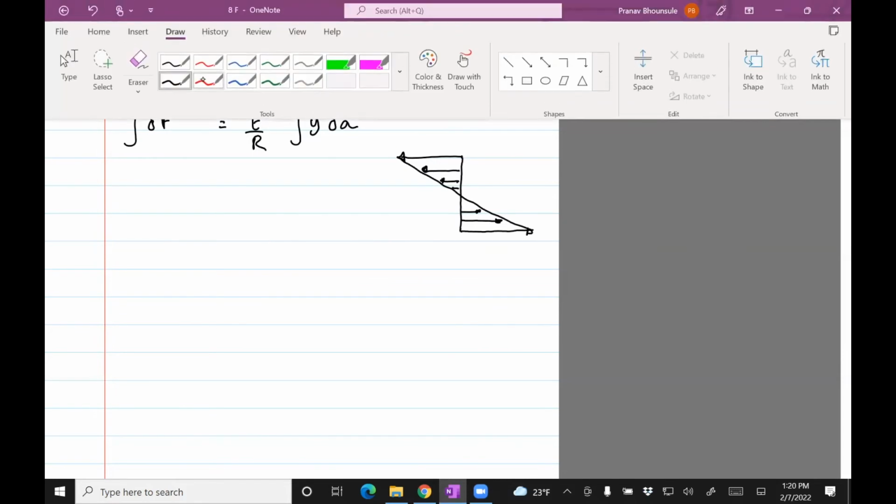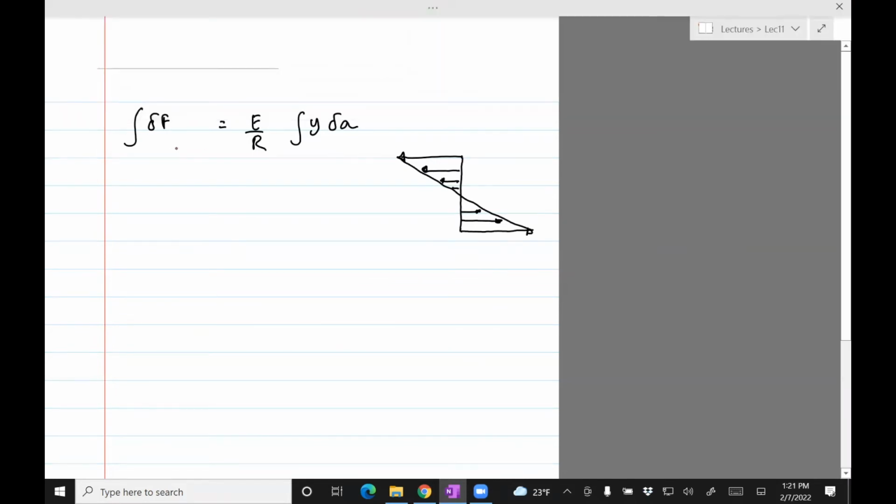So now the main observation we make is that if you integrate the stress, or say integrate the force over the whole cross section, some part of that is the top of the beam is under compression, the bottom of the beam is under tension, and the net force in the beam is actually 0, right? There's no actual force pulling the beam because it's only subject to a pure bending moment. So this integral here is actually 0. No force in the x direction.